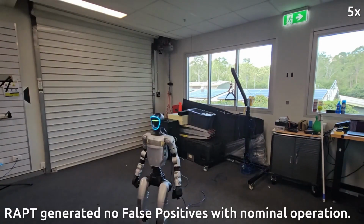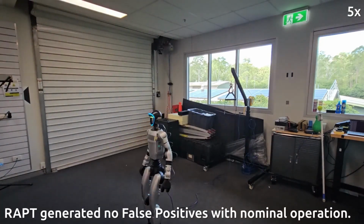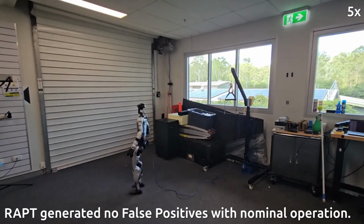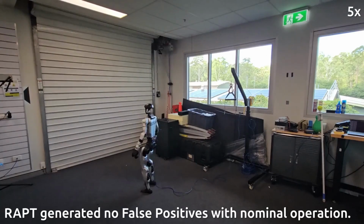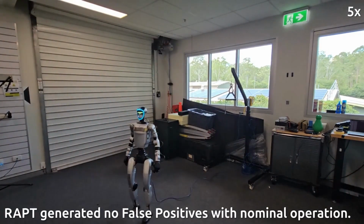Here we show nominal real-world executions with RAPT running online. Despite external pushes, no false positives are triggered. This robustness comes from training RAPT on domain randomized nominal data, allowing it to ignore expected disturbances while remaining sensitive to genuine anomalies.